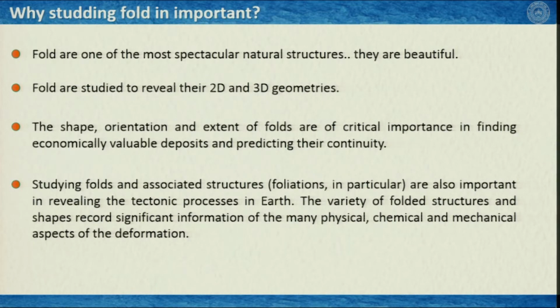Therefore, if you see different parts of this fold in different places, it is very important that you construct first their 2 dimensional and then 3 dimensional geometries. It is not only field work; you have to collect data like dip, strike, trend, plunge of related structures, and then plot it on the stereonet, and then you can construct the 2D and 3D geometries. This you must learn from your field studies.